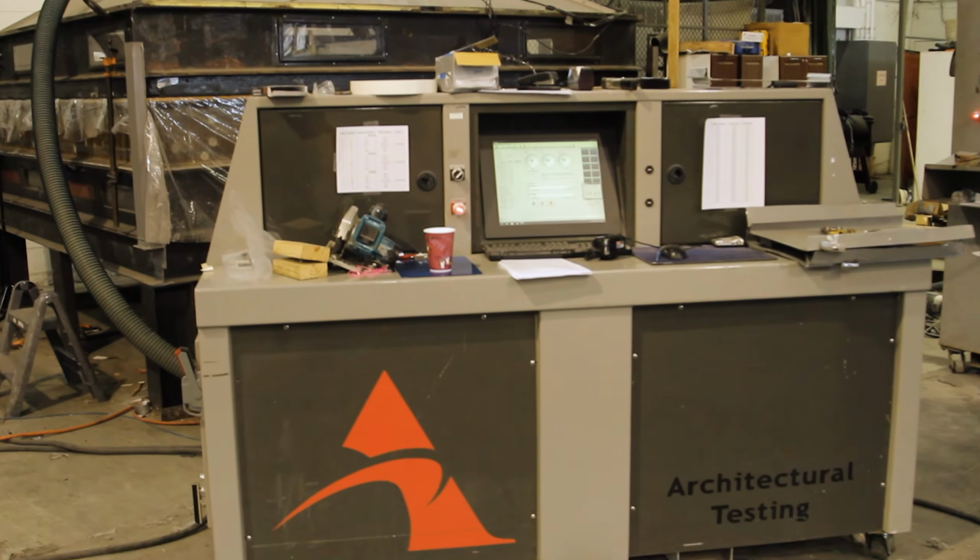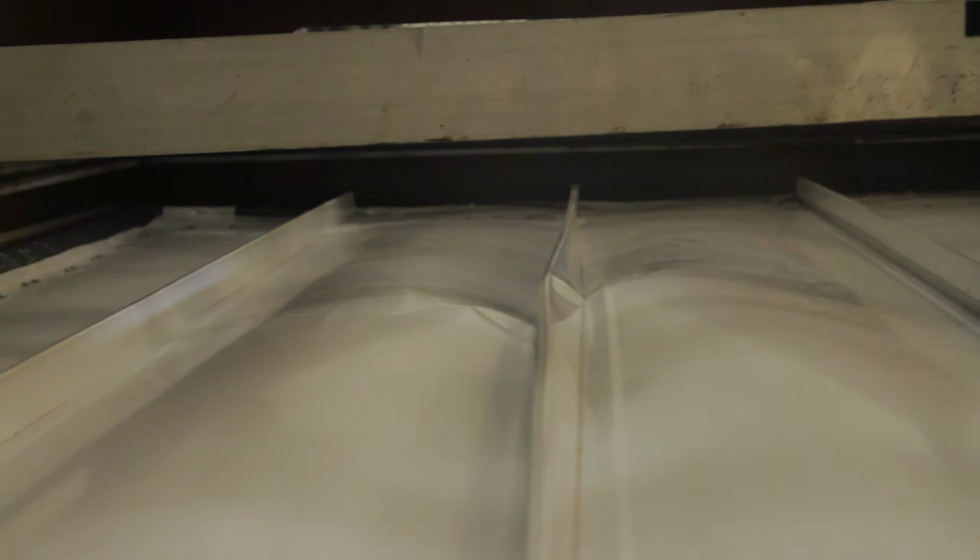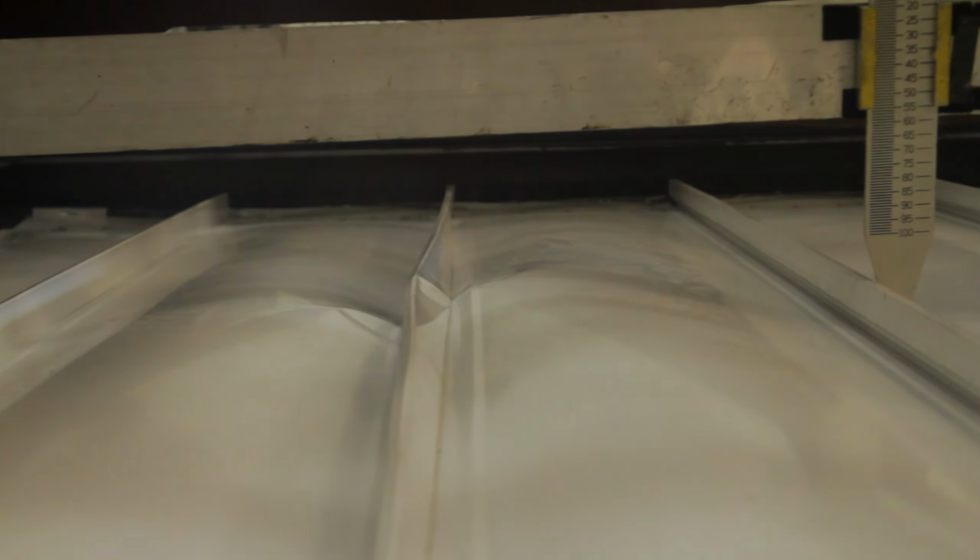You look at the chart, and we talk about it in the video. You talk about the mean height, the exposure category it's in, and those are pretty easy to figure out. We can talk about those, and the wind speed that you need to meet, and it'll give you a rough estimate as far as a design pressure. If you can meet those pressures well above with the panel systems that we have to offer, it's probably a pretty safe bet that you'll be able to meet the design calcs when it's done. If it's right there on the edge, it's something to have a conversation about.